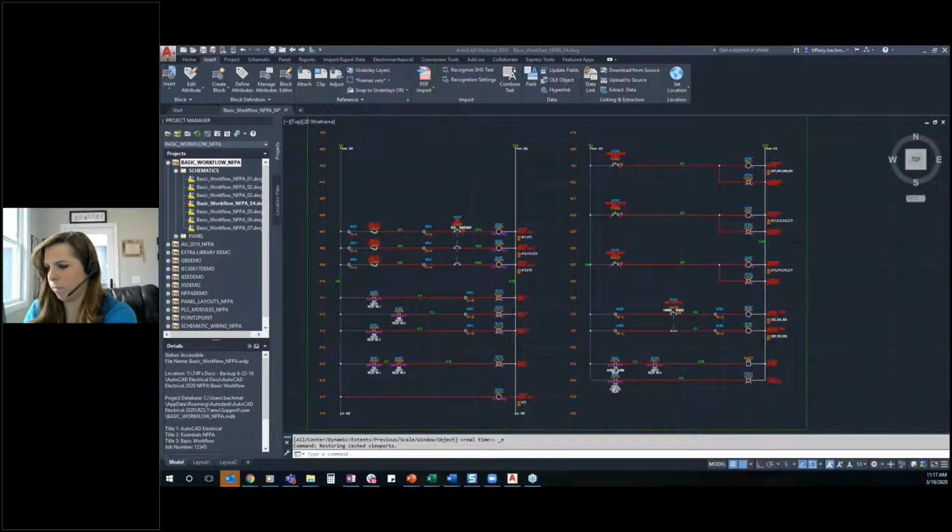Maybe do another get from Vault to try to refresh that file. Maybe try to just remove it, re-download it, things like that, just to resync that workspace to make sure that the latest copy of that file is where it should be. And again, logging out, logging in sometimes will clear up some of those as well. So thank you, Mark.